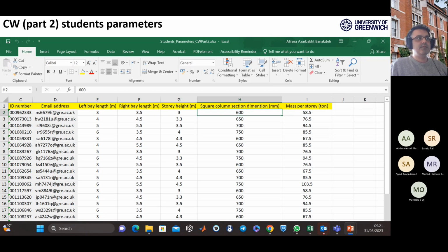and it has g as an acceleration, you can multiply this by g, which is, let's call it 10, and 1 ton times 10 would be 10,000 Newton, right, as a force. So be careful about the definition of mass and force. Here we are dealing with mass, and force is something different.